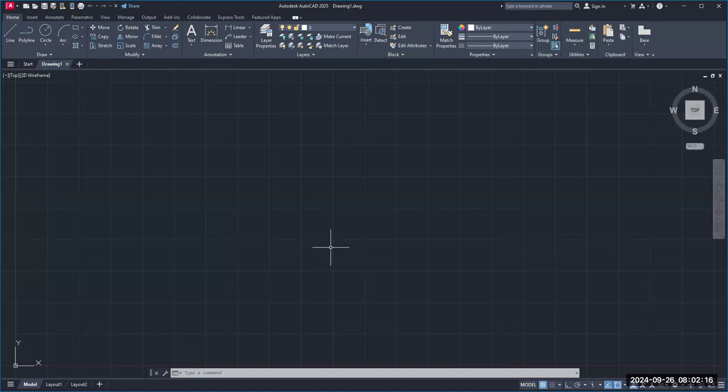Now, when you use AutoCAD, by the way, you can do 3D models. I mean, actual 3D models in AutoCAD. I'll save that for another day. We'll do something simple just to give you some experience. But we're going to make a two-dimensional drawing here. So we're going to use what they call the method of projections, so that you can project points of interest or lines of interest from one view to the other.